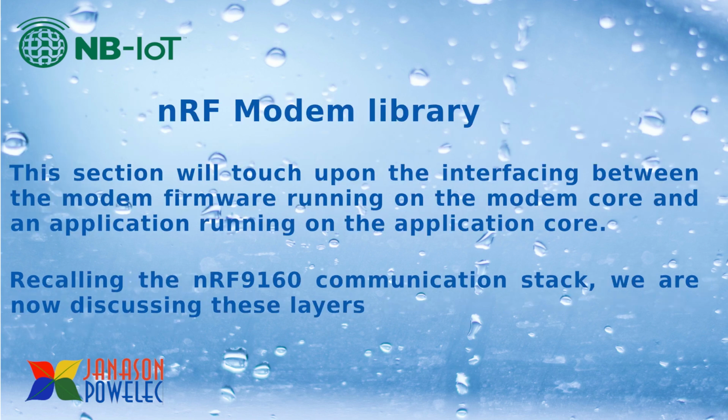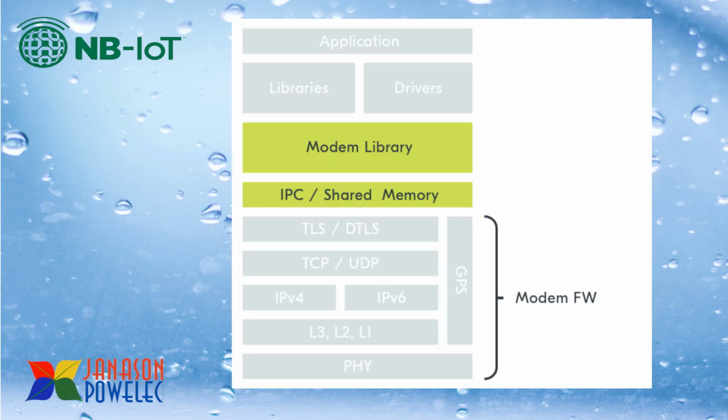NRF modem library. This section will touch upon the interfacing between the modem firmware running on the modem core and an application running on the application core. Recalling the NRF 9160 communication stack, we are now discussing these layers. Now we are going to discuss modem library and IPC shared memory layers.